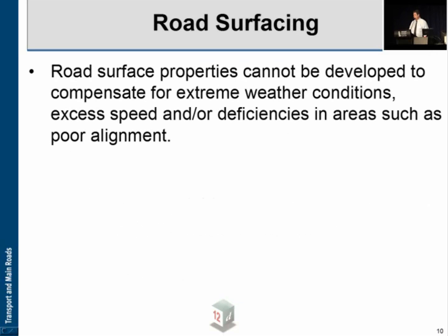So that's why when you have a problem, it's basically go back and review your geometrics, and that's why it's more important now to solve your aquaplaning potential problems very early in the road design process. Get rid of them first and then fix your alignments, and then you can build the rest. If you've got to go and change it later on because you forgot to do it or some problems have come up, it's very hard to then alter the whole design.